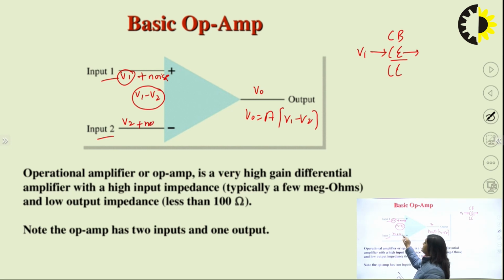If the same noise is introduced at both terminals and the difference is amplified, this noise will be cancelled out and will not be amplified in the case of the Opamp. But in the case of a transistor there is no strategy by which this noise can be removed.